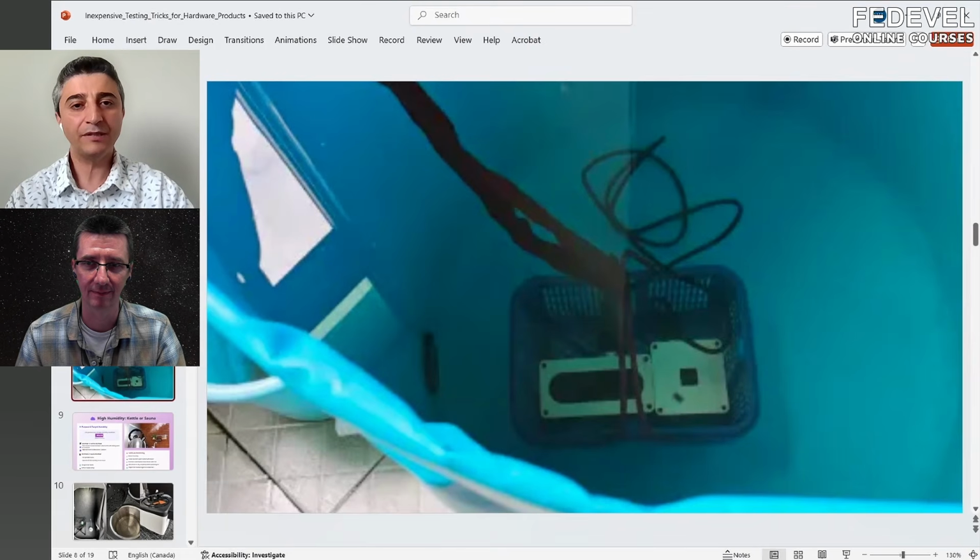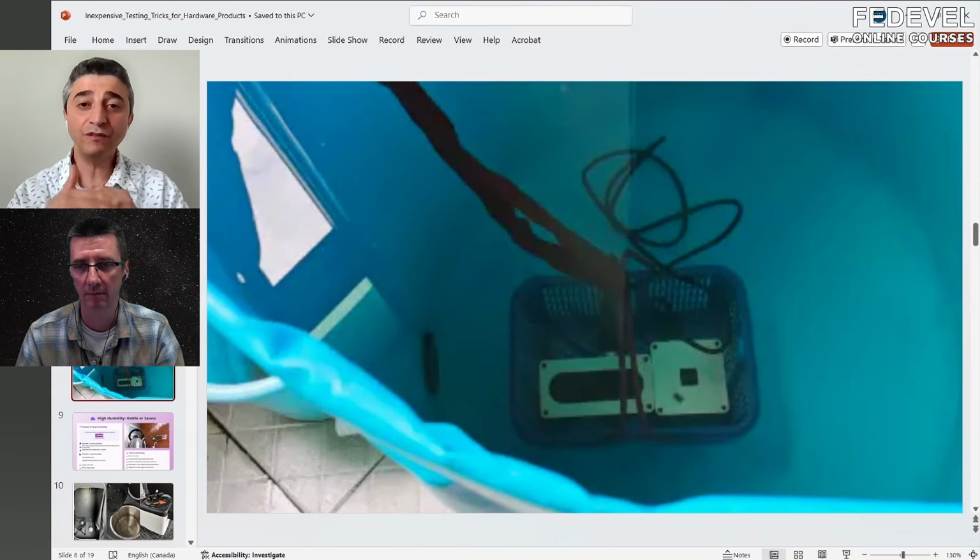The answer is, let's say your device is not meant to operate in water conditions, but in raining conditions. If dust accumulates across some sensors, like a light-based sensor, let's say a light detecting resistor, and you have water and dust building on top of it, maybe you want to make sure the surface of your design is coated with some material to avoid that, because if there is dust buildup, then the sensitivity of your sensor might be affected.